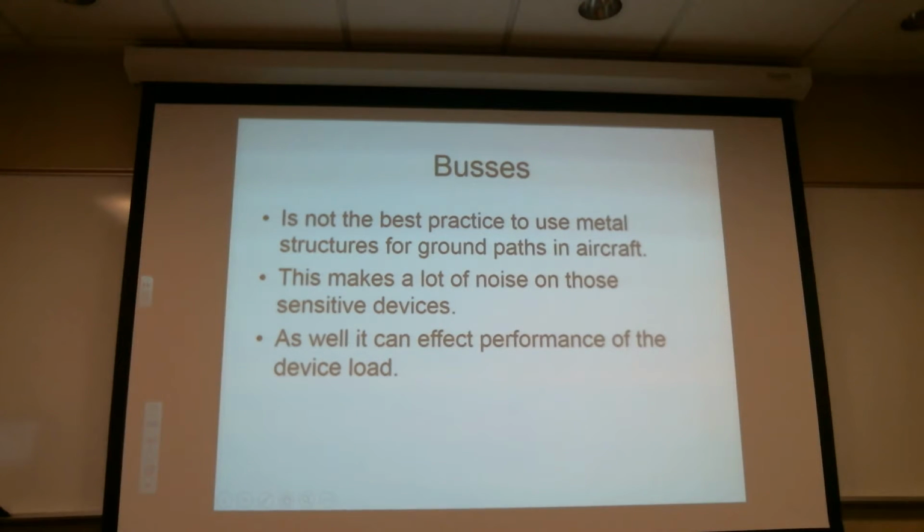So the starter was seeing, instead of 13 volts, less, because the ground strap of the vehicle was partly compromised. Everything else would work fine at their 10 or 15 amps. But when you hit 300 amps across that thing, they were dropping 4 or 5 volts on the starter. Well, what happens to the starter motor? We'll get into this a little bit later. It didn't have enough voltage, so it didn't produce enough counter EMF. So its resistance never went up high enough. Even though it had resistance at that joint, it still had way more current. The total fully running loaded current was a lot higher, which was burning it up.